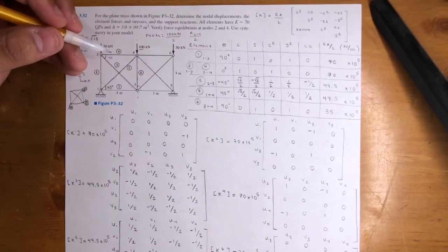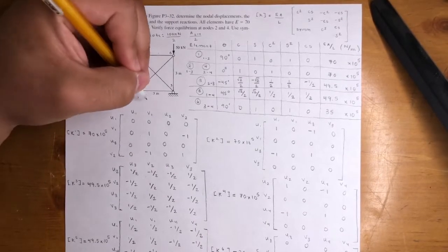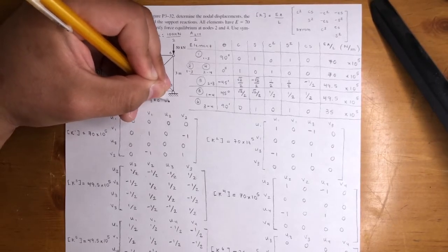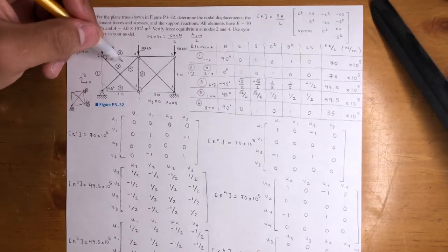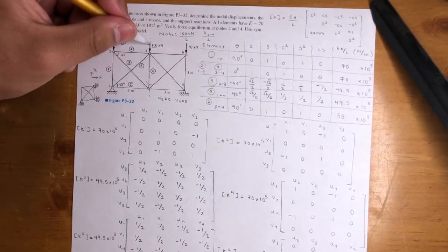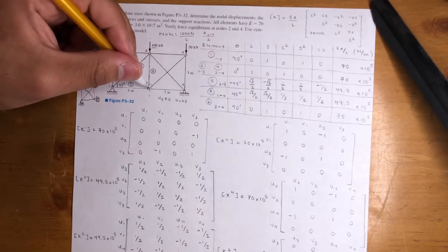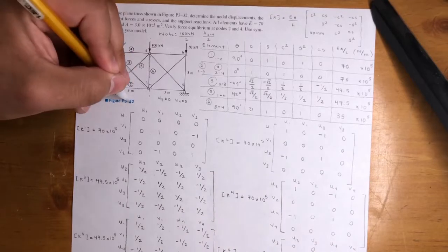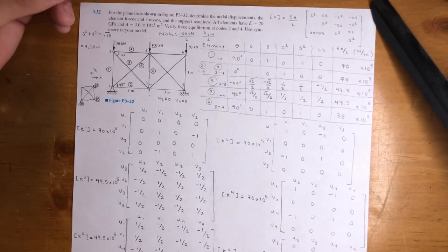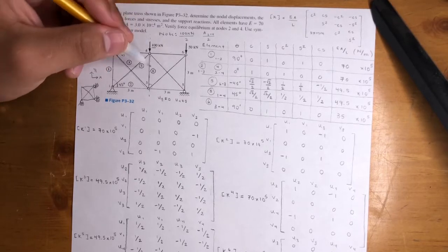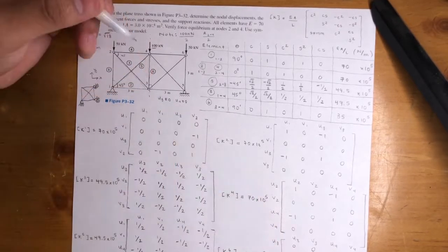So this is what we're going to do. Let's apply that boundary condition. I'm going to make a little note right here. Sorry if it's a little squished up, but U3 is equal to 0 and U4 is equal to 0. That's an assumption we're making. We're analyzing this structure as an engineer, and if we're pushing down and it's symmetrical, I'm going to assume there's no movement in the X direction. There probably is. If you saw the other problem, 330, the one we just did, there was, but it was very little, about a third of a millimeter. Think about how small that is. It's negligible, so that's why we make this assumption, and that helps us with the boundary conditions.